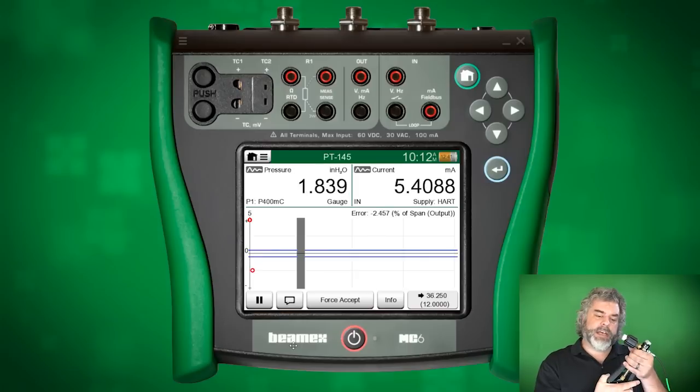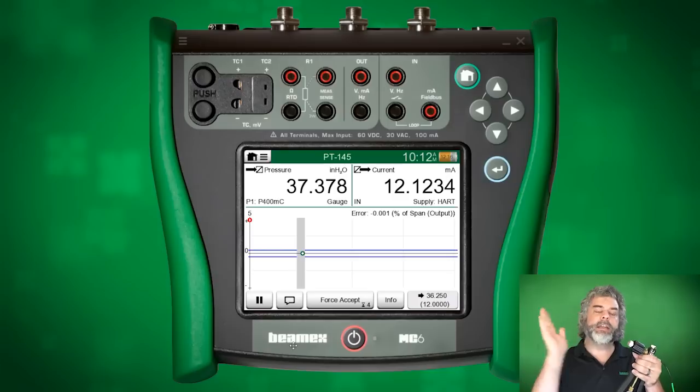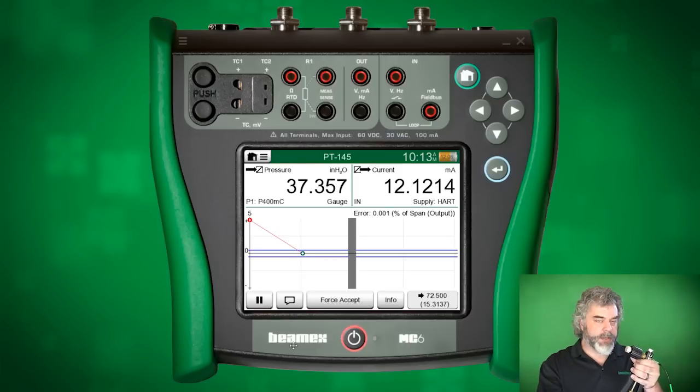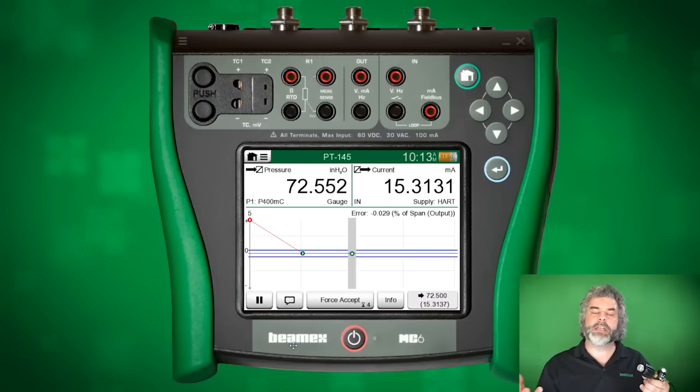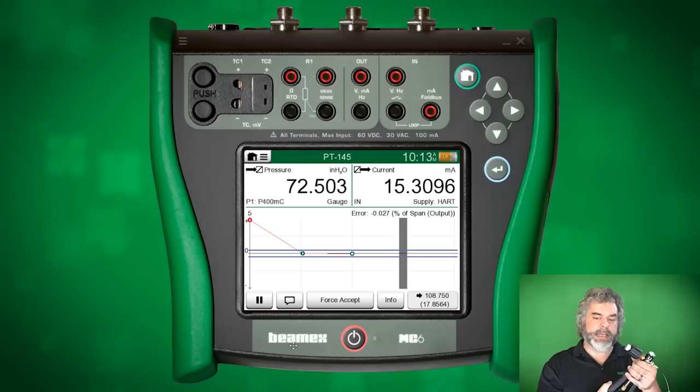And I have this set up to give me a gray bar of plus or minus 4%, and I'm just letting go. I'm getting it into the gray area. So the bottom right is my actual target, but I told the calibrator to visually show me plus or minus 4%, just to give me a target, because we don't have to get exactly on that value because the error is based on a calculation of the input against the output.